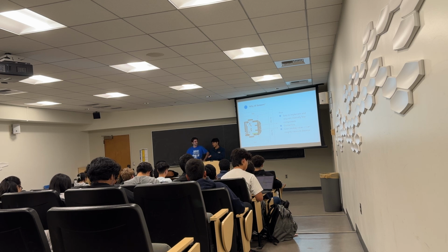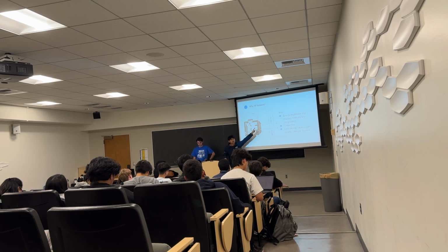Essentially, for all these pairings, you want to turn one of the IR emitters on and have one pair working at a time. Or else if you're emitting light right here and receiving light from here, this light might interfere with this one, so that's not good. So we turn on one pair at a time. But for the pairs, I'm pretty sure the IR emitter emits at a time interval so it doesn't interfere with the light you're getting.